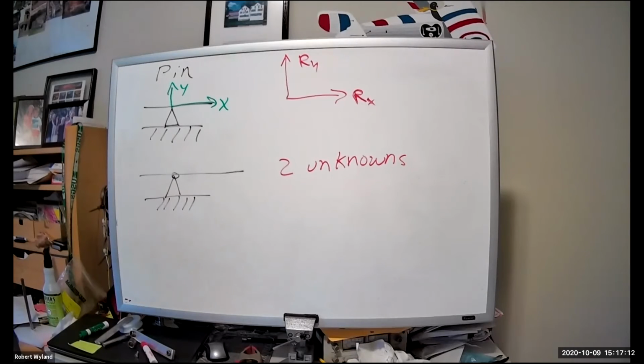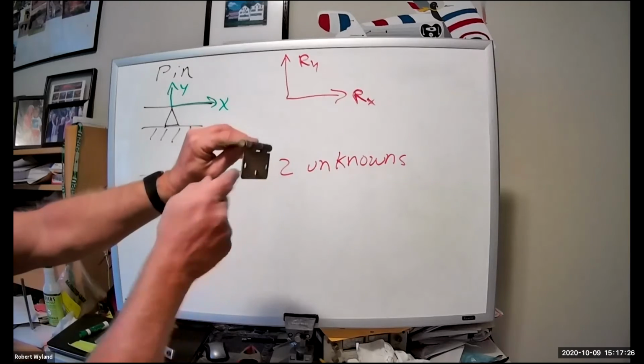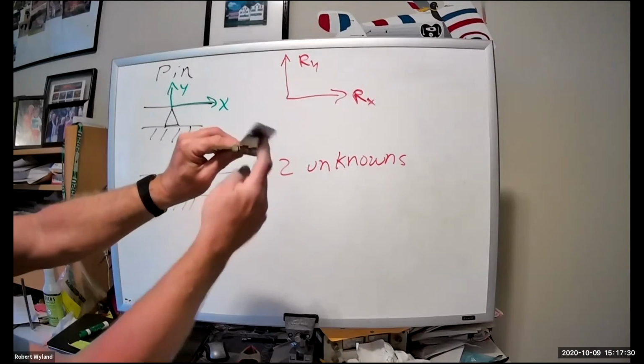Rob? Yeah. So these reactions are just forces, right? They are forces that could exist in that joint. Okay, possible forces. Yeah. So like when I talk about there was no moment, if we try and put a moment on this, it's going to swing, it's going to move. It's not going to be, as we say, static.